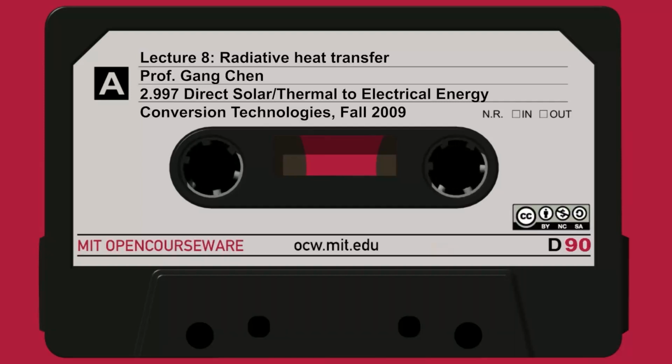But let me just make one comment here. Although what comes in, the overall spectrum of, for example, solar radiation coming to the surface depends on the temperature of the sun, right? But the spectral absorptivity here doesn't depend on that. I can have thermal radiation coming to the surface, or this laser beam coming to the surface. That's my intensity, right? And this temperature is really the temperature of the material. It's not the temperature of the source.